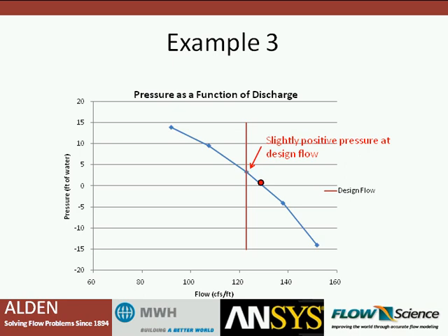And interestingly, as we move up on the discharge and go about 20% above the design flow, we get a pressure on the surface of the spillway of about -15 feet of water column. The vapor pressure of water is at around -30, depending where you're at in terms of elevation. So at -15, we're going to start seeing some cavitation problems because of the roughness of the spillway. It'll actually cavitate at slightly lower or higher pressures than the vapor pressure of water.